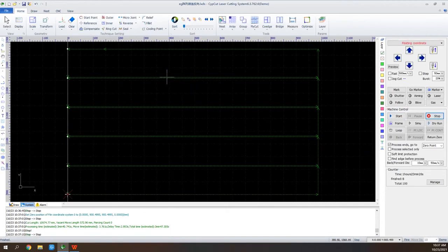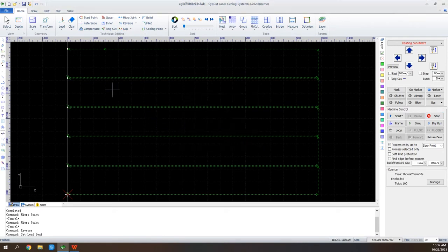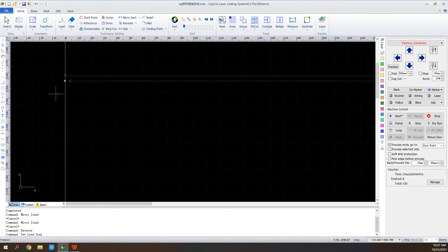Down below, this is the gap feature here. In the drop-down menu, we can see the gap. Select the graphic and click it when we need to set a gap at the end of cutting path. Here is the gap. On the control rail, we can seal the gap if we don't want it no more. There are also overcut and multi-cut. Overcut is for making sure the whole part was machined, and multi-cut is for an obvious marking.